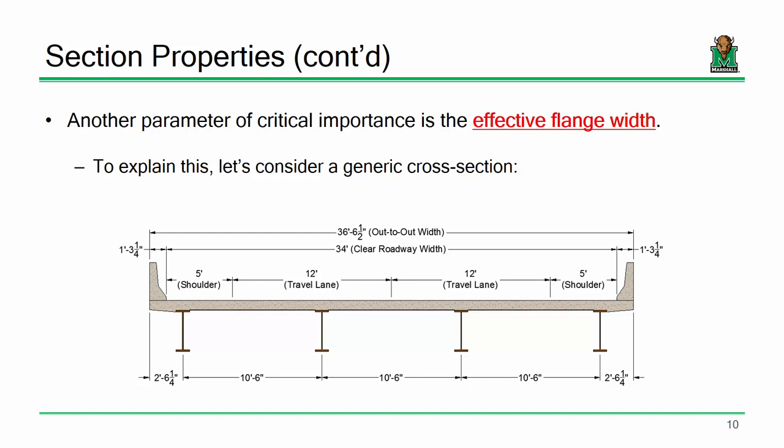Okay. Now, when I'm evaluating a given beam, let's say this beam or maybe this beam, if I'm looking at the composite beam, it's the steel plus a portion of the deck. The key word is a portion. For this beam, let's say I'm looking at this second beam over, the question I'm trying to answer is how much of that deck is applicable for this given beam? Is it this much? Is it this much? How much of that deck can I consider effective for that beam?